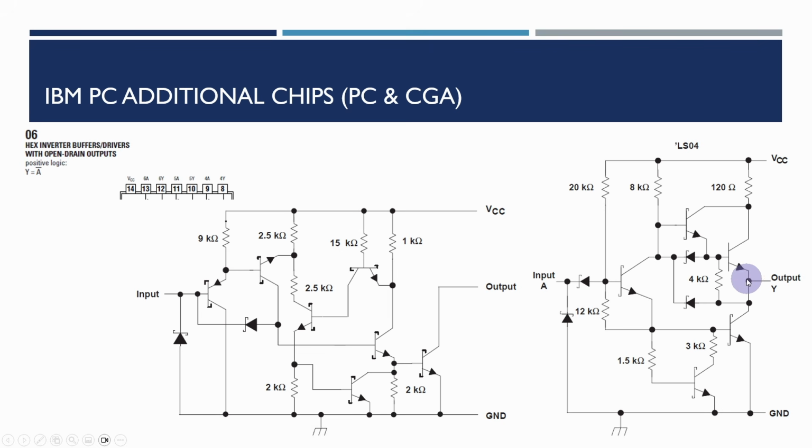We've got both the pull up to high voltage and pull down to low voltage. You can see here that this part is really missing. In order for us to actually get an output here, if we wanted to put an oscilloscope or a logic probe on here and we didn't do anything else, we wouldn't actually see anything. What you need to do is put some sort of pull-up resistor either to 5 volts or to whatever voltage you are using.